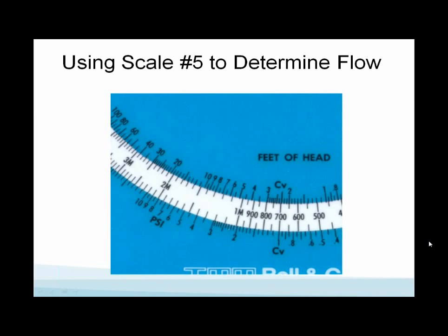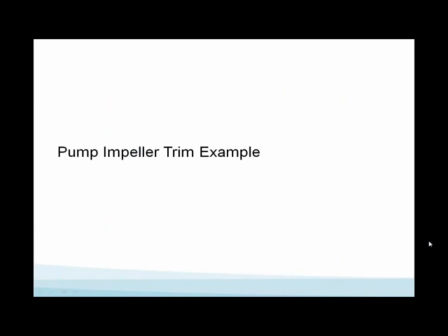The manual chart takes interpolation, which is a little hard. Us older guys are used to that. You kids are probably used to computers. Go to your computer and run the same system. It's much easier to read. Just go there and put in the known flow and the known head, then put in the unknown pressure drop, which is 11 pounds in this case, and it will give you the unknown GPM, which is probably going to calculate at 2,309 GPM, a little bit more than 2,300. Is that accurate? Your young kids would probably prefer the Windows-based version or the little iPhone to calculate this, but it's a beautiful tool to have and understand.